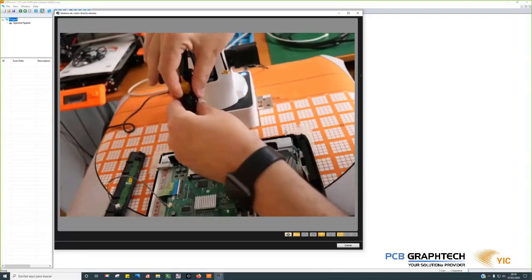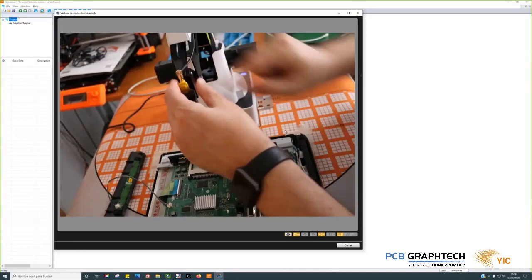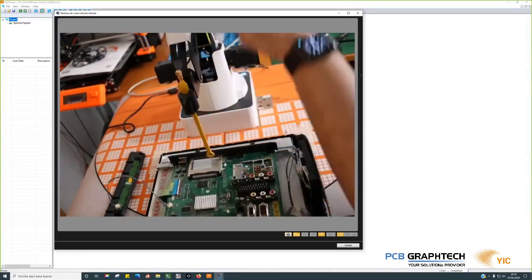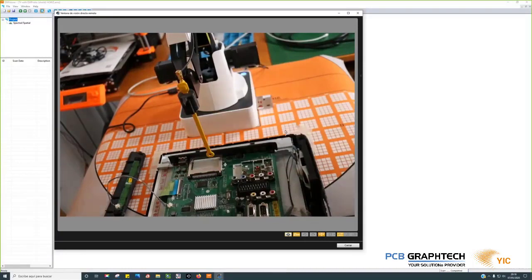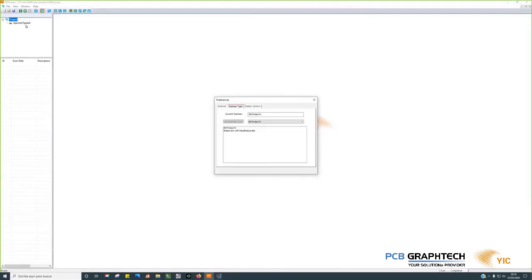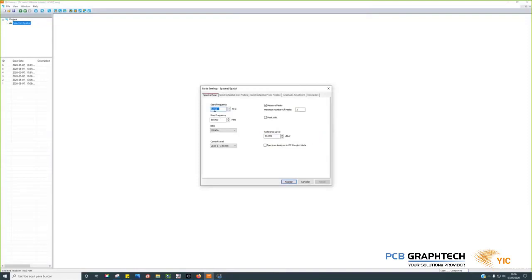And I connect the output of the probe so the radio frequency can go to the spectrum analyzer. Now, here, I am going to do a spectral spatial scan. The first thing to do is to establish the frequency range. For example, 1 megahertz to 80 megahertz in 120 kilohertz resolution bandwidth in the spectrum analyzer.